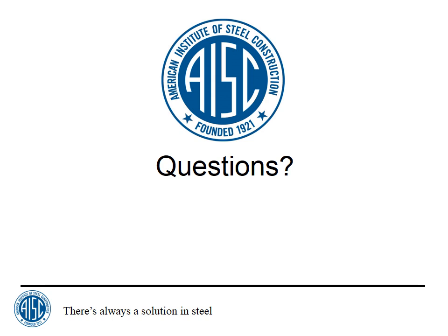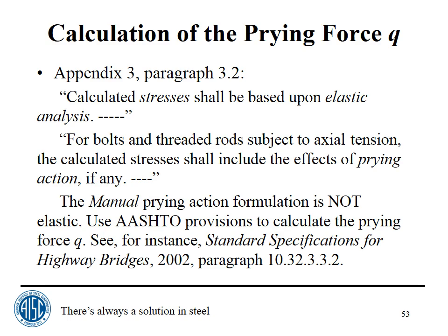Okay. All right, I'm going to move to slide 53. Your discussion of Q, and the question is, which values will give you a higher prying force Q, the elastic method or inelastic or plastic method? Well, the method that's given here in the manual is inelastic or plastic.